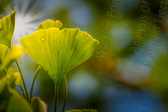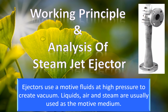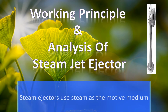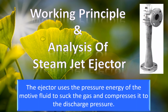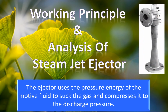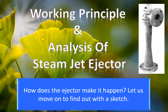Working principle and analysis of steam jet ejector. Ejectors use motive fluids at high pressure to create vacuum. Liquids, air and steam are usually used as a motive medium. Steam jet ejectors use steam as a motive medium. The ejector uses the pressure energy of the motive fluid to suck the gas and compress it to the discharge pressure. How does the ejector make it happen? Let us move on to find out with a sketch.